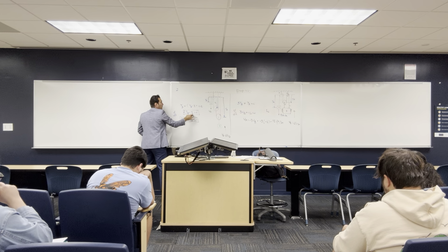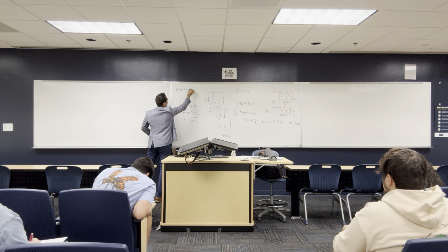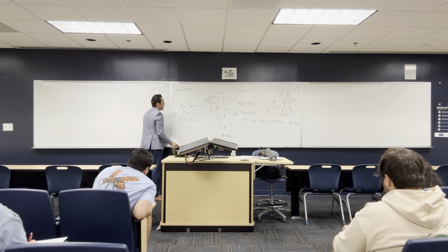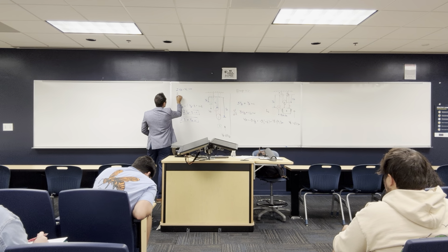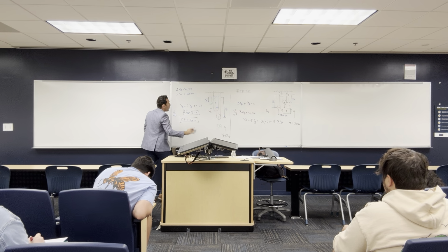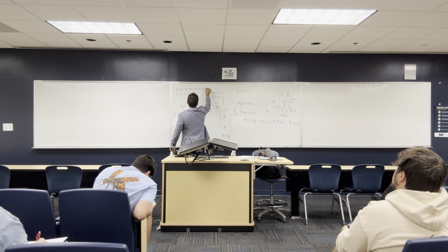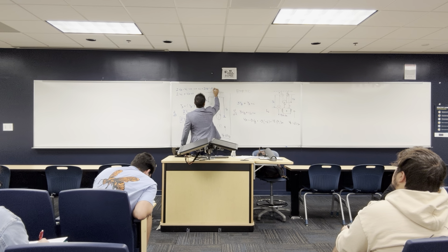If you take d/dt of this, it's going to be 2vB minus vC equal to 0. dy/dt is the v. The derivative of the constant is going to be 0. And then the second equation, 2vC plus vA is going to be equal to 0. What I have here, I have vB. So I can substitute in this equation, and this gives me that vC is equal to 2vB, and this is 2 by 6. And this is going to be 12 feet per second.